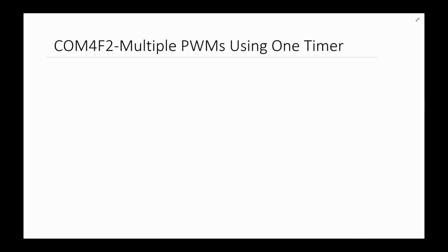Yes, the answer to that question is yes. And in this video, what we're going to do is use a single timer, one of the 4 timers in the PICmicro, or whatever timer is available in the particular processor you're working with. And we're going to use that to create pulse width modulation, multiple or however many we need.